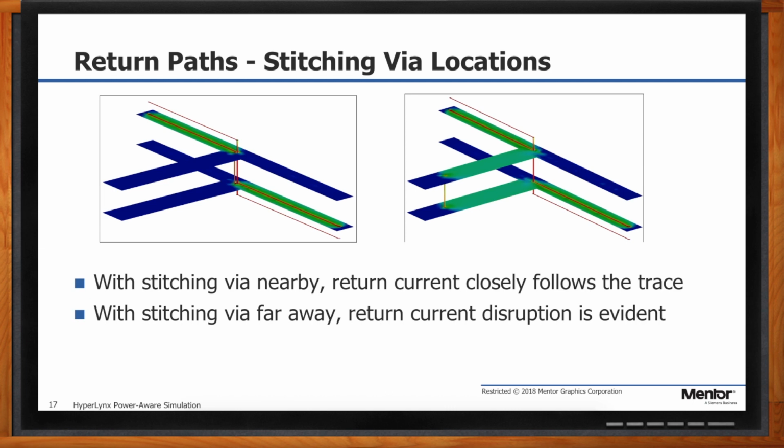So if you think of it like a waterfall diagram, you can imagine that there's literally water on that top plane, draining through that hole and going to the bottom and then coming around. The important point here is that when I have a signal flowing over a plane, that return current is just as important as what we think of as the signal itself. Really, the signal is the combination of the trace and the return plane, or the return path. It doesn't matter whether I interrupt the electrical trace itself or the plane beneath it; either one is going to end up affecting the signal. Most of the time, we just pretend that these planes are perfect and we don't have to worry about this stuff, but that's not what really happens.